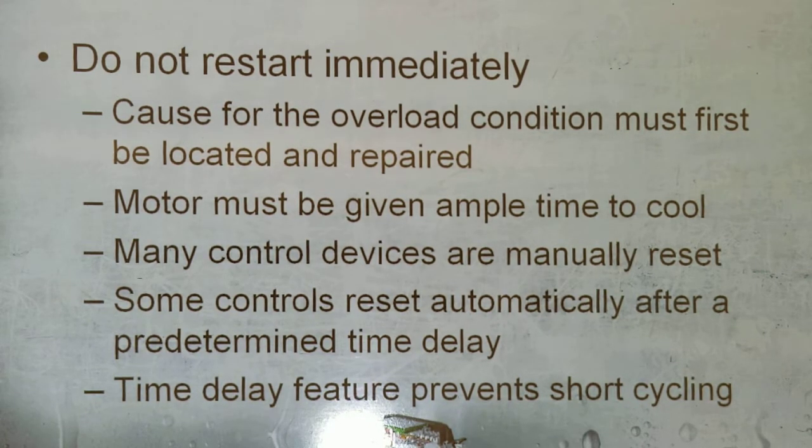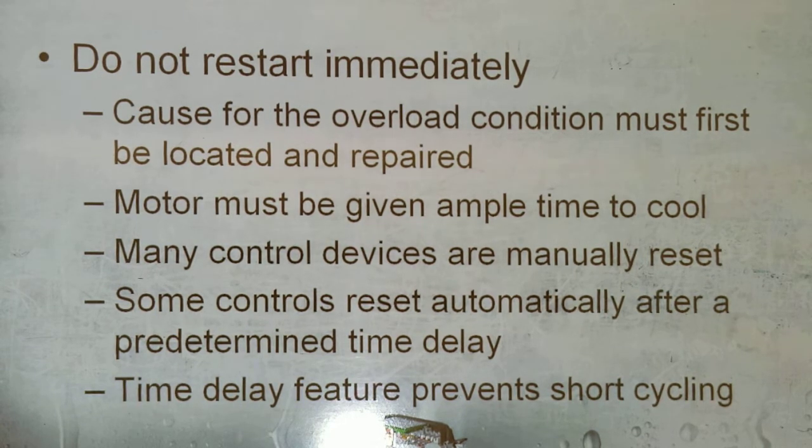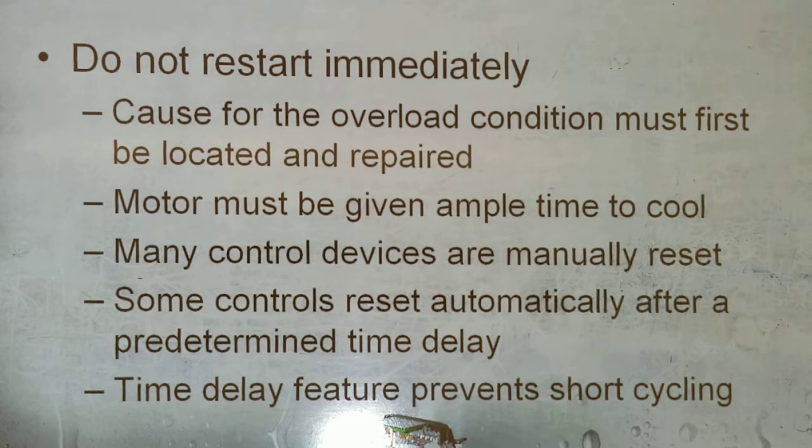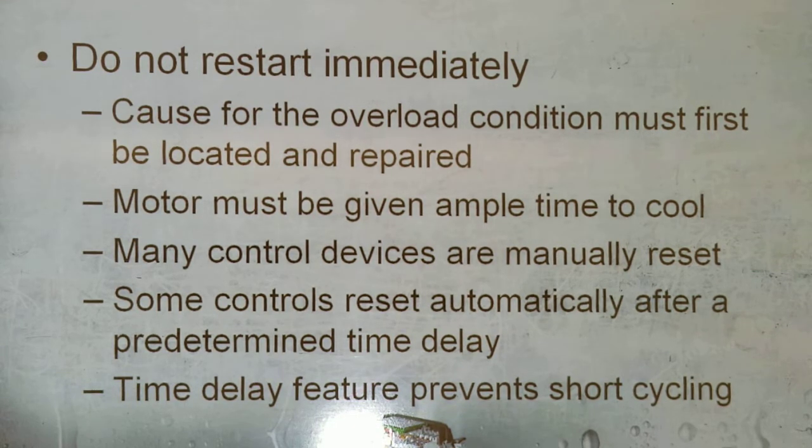Restarting the motor. Do not restart immediately. Cause for overload condition must first be located and repaired. Motor must be given ample time to cool. Many control devices are manually reset. Some controls reset automatically after a predetermined time delay. Time delay feature prevents short cycle.